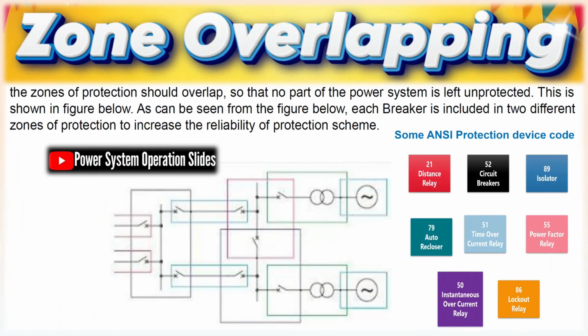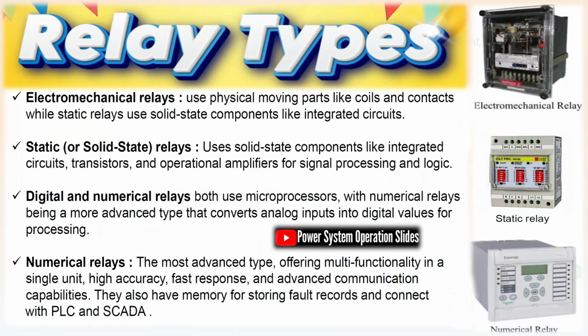Low versus high impedance ground fault. Low impedance faults produce high currents easily detected by protection devices. High impedance faults produce low currents that may remain undetected. Surface conditions often dictate impedance type.